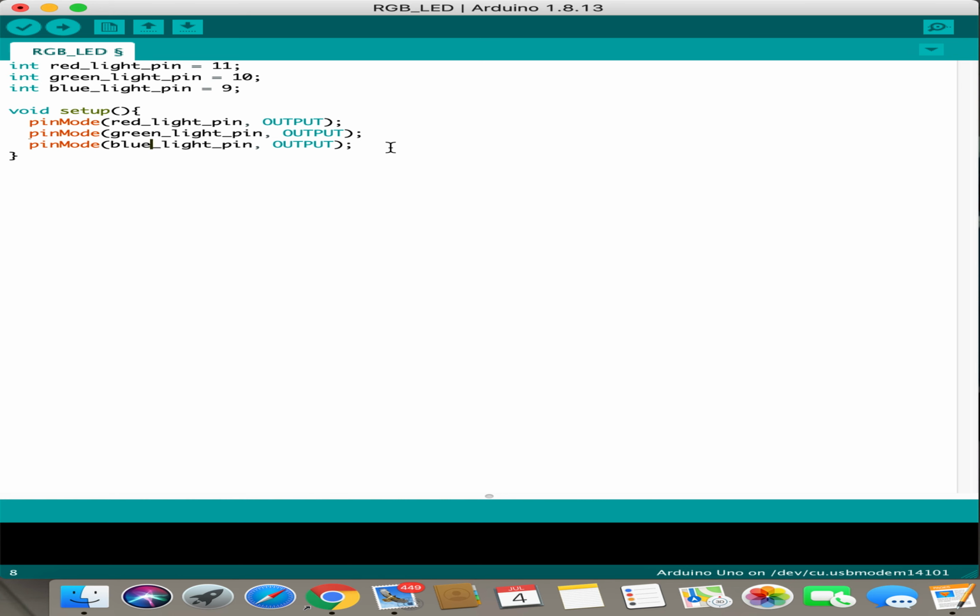You might be asking why we're not directly giving numbers as inputs. And the reason for that is that it increases the readability of our code. And the pin values are going to be used later on. So if we make minor changes to our variables, we won't have to reassign everything.